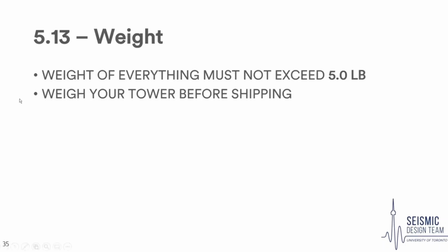Super important. We decided to use thinner plywood this year for our base plate because we were worried that if we used the 1/4 inch plywood that we normally use, we would get disqualified for weight. So that's a big consideration. If you build a test tower, weigh it just to see how your regular tower is doing. Before you ship your tower, weigh it with a scale so that if we're at 5.5 pounds, we know we're going to have to take something off, because it's better to get 25th than disqualified, even if you have to take a bunch of stuff off.